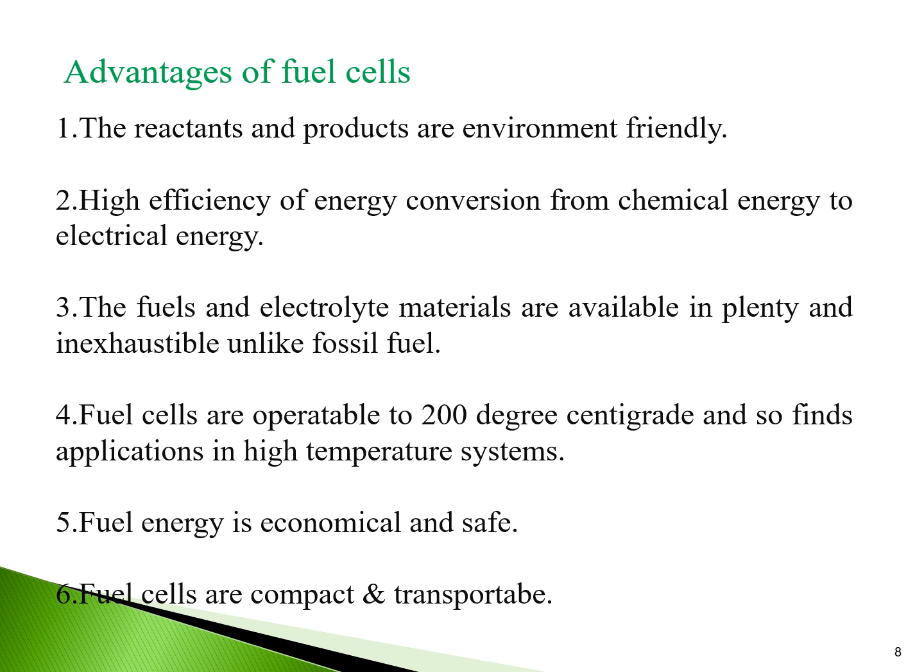Advantages of fuel cells: the reactants and the products are eco-friendly. It does not harm the environment. There is a high efficiency of energy conversion from chemical energy into electrical energy, and the fuel and the electrolyte materials are available in plenty, unlike our fossil fuels. So we can rely on this, and we can go on to use it in our vehicles also. Fuel cells are operable up to 200 degrees centigrade, and find applications in higher temperature systems also. And fuel cell energy is economical and safe. In the same way, fuel cells are also compact and transportable.